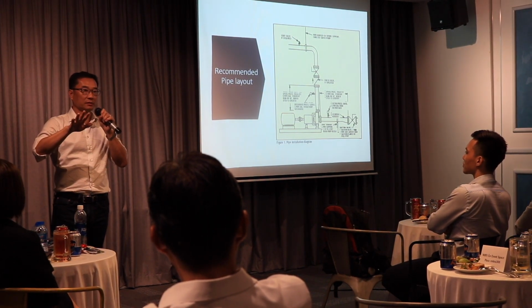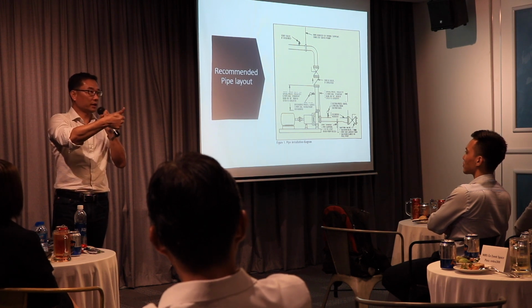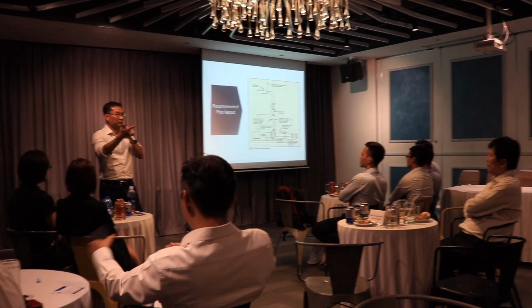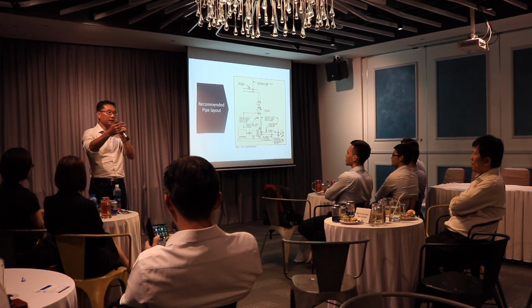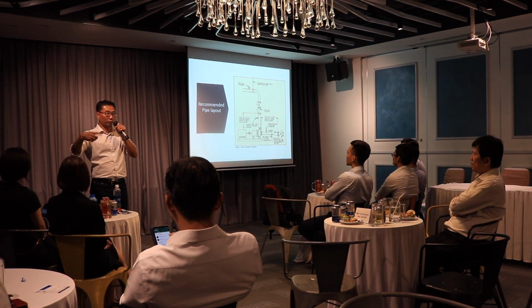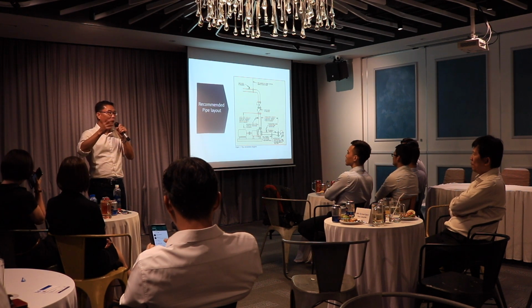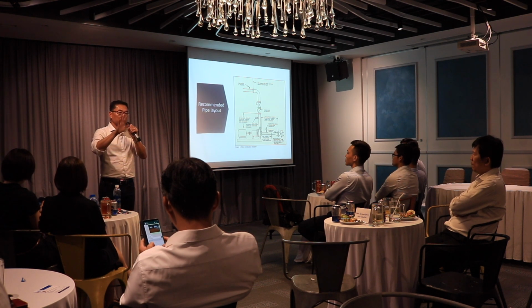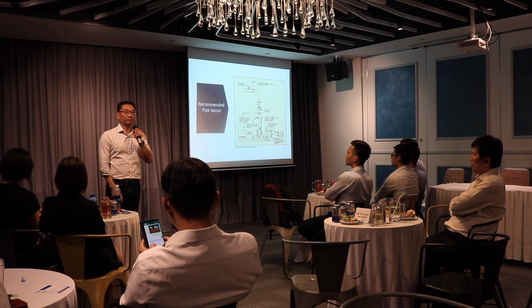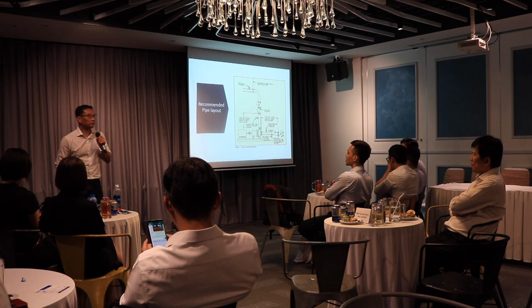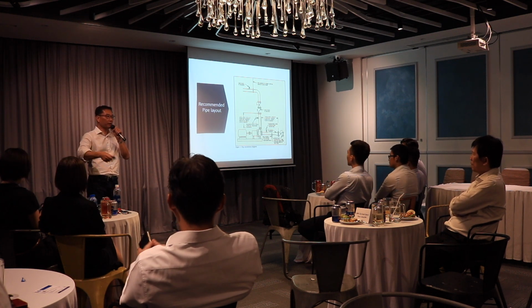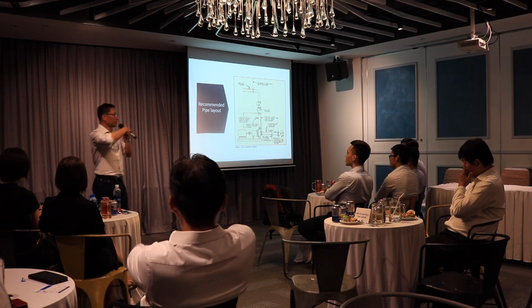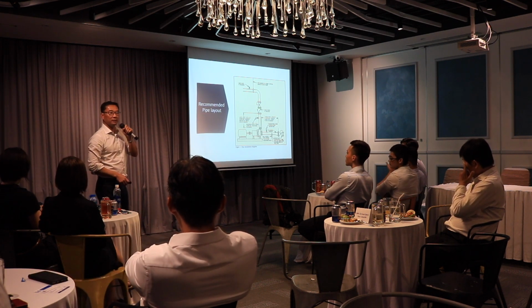and the suction. Cavitation is about suction. Right? Your vortexing is about suction. Right? Your water hammer, obviously this has to do with the rotation where it stops suddenly, acceleration, but in some way it's also related to suction. I guarantee you, out of 10 times you have a problem, 9 times it is because of the suction. First thing you do, you go down there, you look at the suction. That's all you need to do. The rest is just mechanical failure, warranty, the manufacturer not putting the impeller trimmed to the correct size.